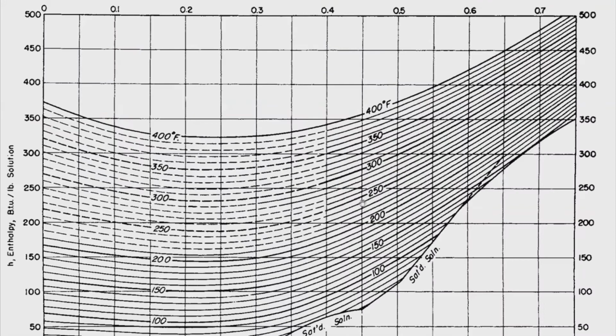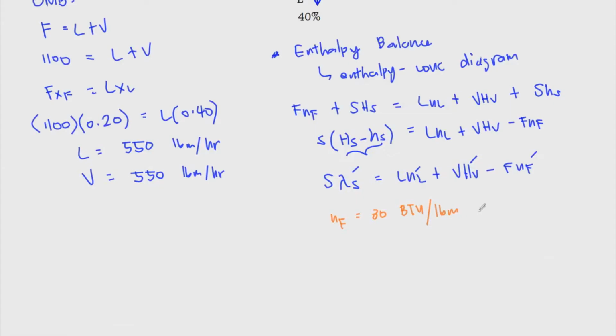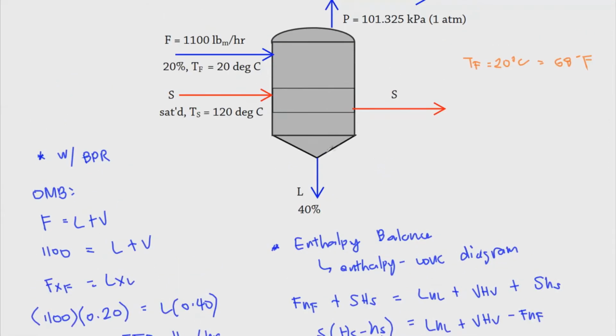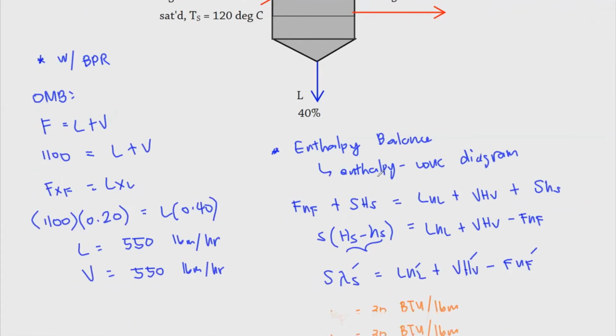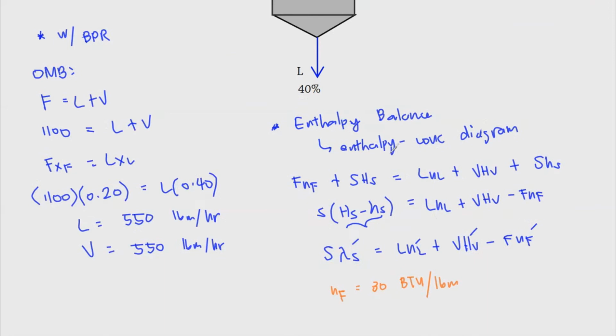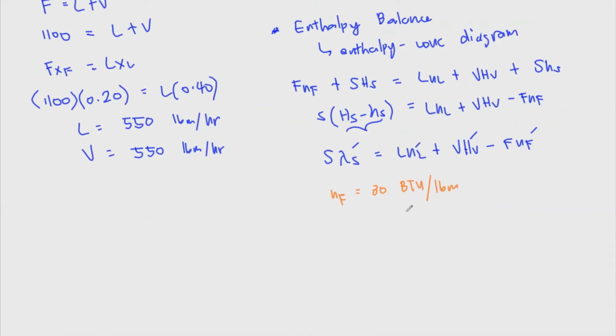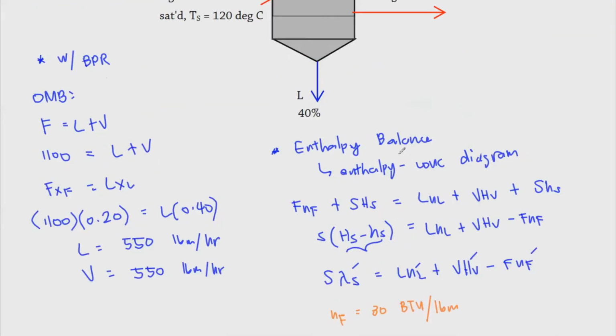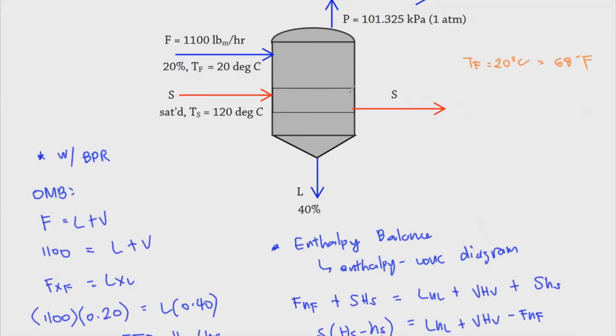Okay. Now we proceed with our liquor. Now we know that our liquor has a temperature which is actually the vapor chest temperature plus the boiling point rise. So you should be evaluating our H sub L at the temperature of, of course, our liquor temperature. But to do that, we need to determine first what would be our liquor temperature.